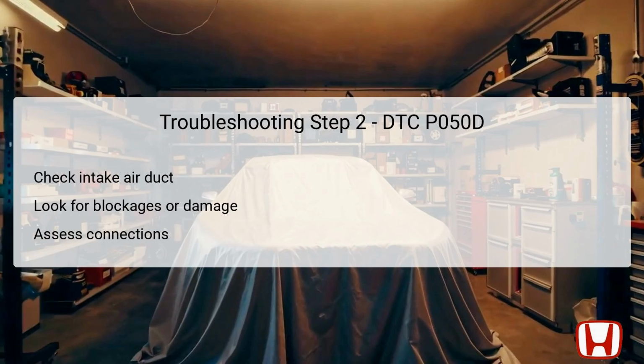The second troubleshooting step involves a visual inspection of the intake air duct. This duct is critical as it channels air from outside into the engine. Technicians should check for any poor connections that might impede airflow or for blockages caused by debris or other obstructions.